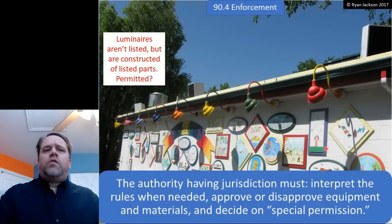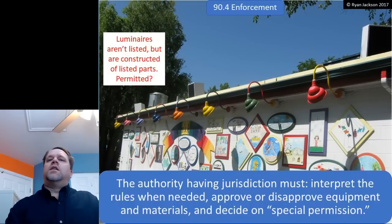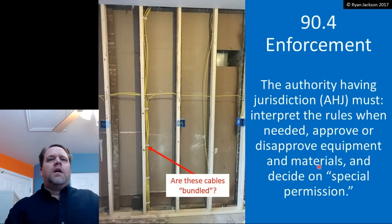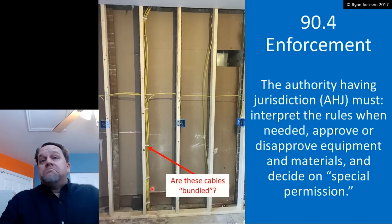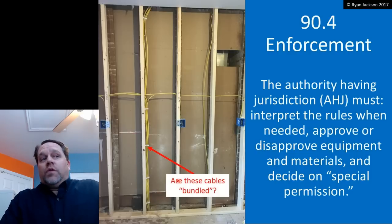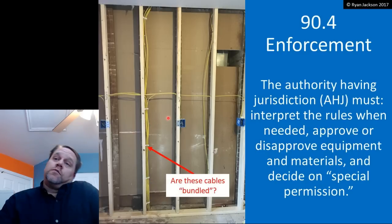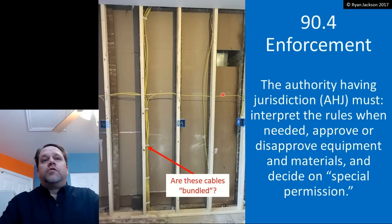So the AHJ, the authority having jurisdiction, they have to interpret the rules. They have to approve or disapprove equipment and materials and decide on special permission. Things like this. Are these cables bundled? I don't know. The NEC doesn't define the word bundled in any general sense, so somebody has to interpret it, and that would be the AHJ. If the inspector looks at it and says, yes, those are bundled, okay, well then they are, because somebody has to interpret the rules.